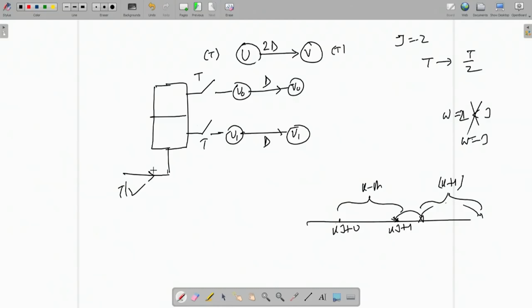This is very important, that unfolding alone may not give you the result, because unfolding has a problem that the delay count per edge goes down. That m was a quotient of the w by j division. Okay, m number of delays, m plus 1 number. So the delay count goes down, and if w is not high and j is high, some delay free paths emerge. In one direction I have got a delay free path. So originally the edge was delayed, but now new edges come up which are delay free.